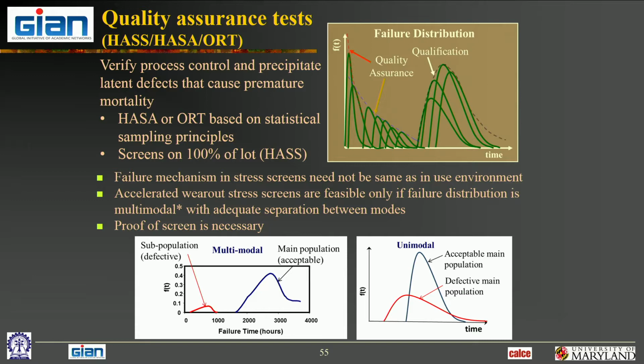How are you going to know which are the bad ones and which are the good ones? So they say, well, all right, run a stress test. The bad ones are going to fail, I'll buy the good ones after that. So give me the ones that survive the test. That's where the term screen comes from. I'm using the stress test to screen out the faulty ones and ship the good ones. So that's the concept behind stress screening.